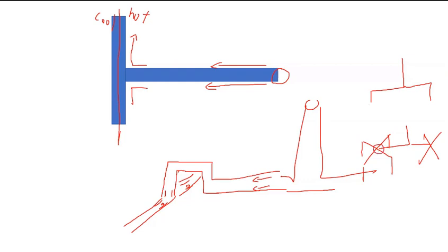They will add a section. So the melt is not split in the other direction at the same level. It's not at the same level, it's at different levels. It adds one section here and splits the melt front. So you can see the melt front direction is from up and down, and then splits to four directions. I noticed a lot of hot runner systems like to use this one.